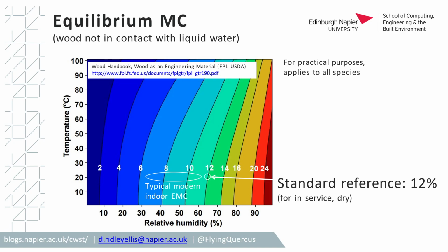Then we'll do the testing, we'll measure the proper moisture content by doing what you have done: make clear samples, weigh them, dimension them, put them in the oven, bring them out, weigh them again. We'd also take the sizes of them again as well, because we're not just measuring the moisture content, we're also measuring dimensional stability of the species of wood. We would normally do that as well.